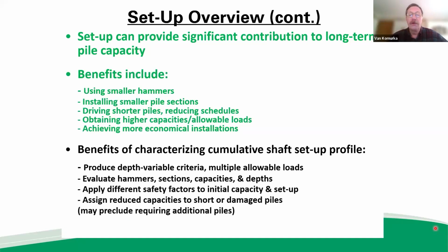So we're going to look at how we characterize cumulative shaft setup, and we'll see what that is. But the benefits of that go beyond simply a setup ratio. You can develop depth variable criteria. You can develop criteria for multiple allowable loads. After the test program, you can evaluate multiple hammer selection, pile sections, capacities, depths of driving.